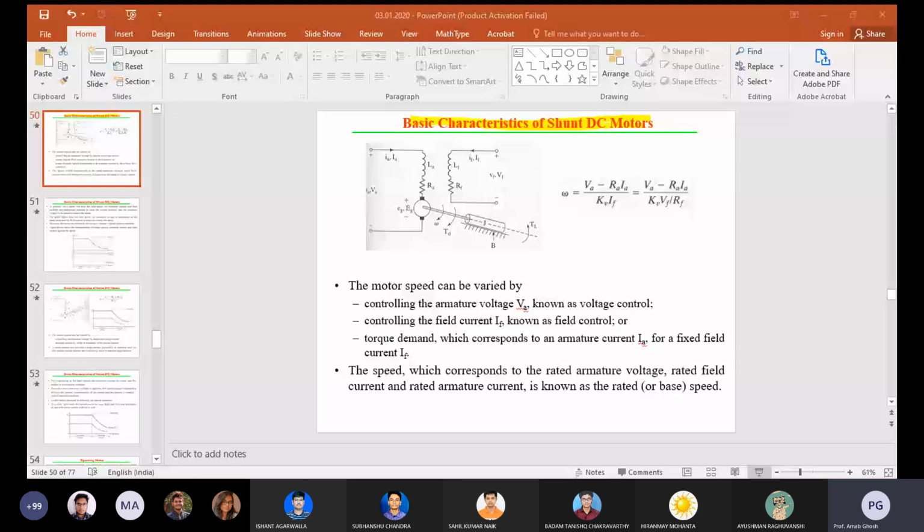The kinetic energy of the motor is returned to the supply. The series motor is usually connected as a series excited, self excited generator. For self excitation, it is necessary that the field current aids the residual flux.